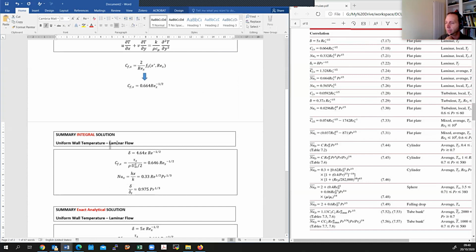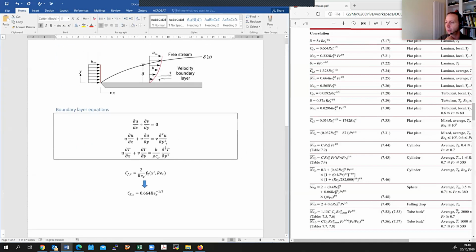Laminar flow means you can make certain simplifications when deriving the solution to the governing equation. For example, here you don't see any time derivative term. A turbulent flow will involve loads of fluctuations which vary hugely in scale. They happen at large scales, perhaps millimeter, centimeter, meter, and they go down to the microscales and smaller.